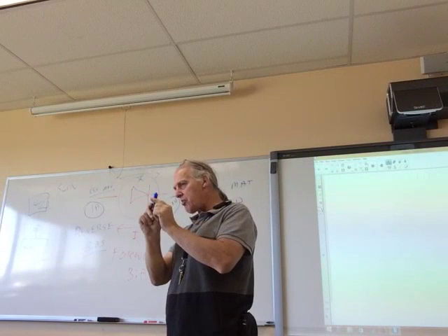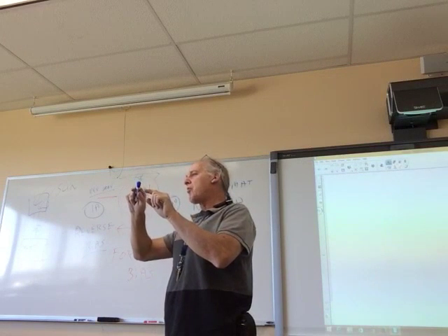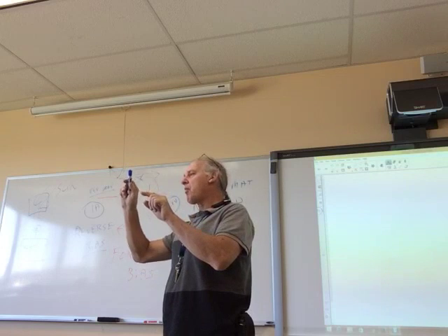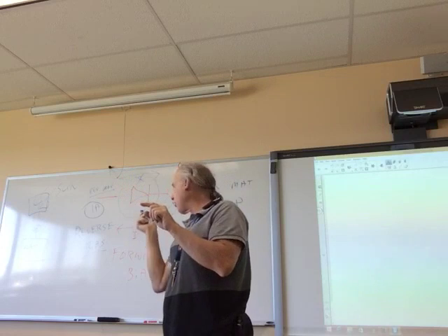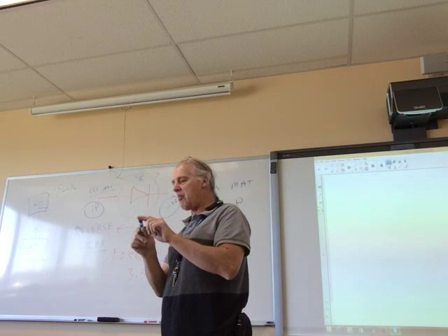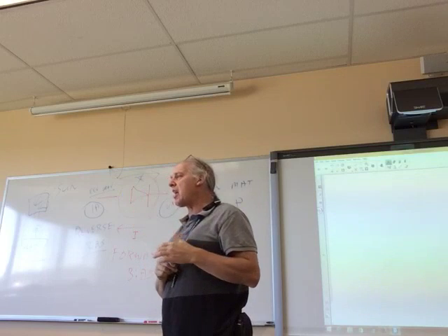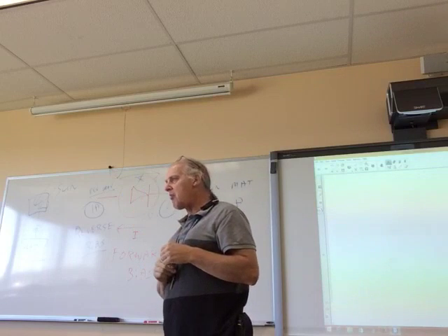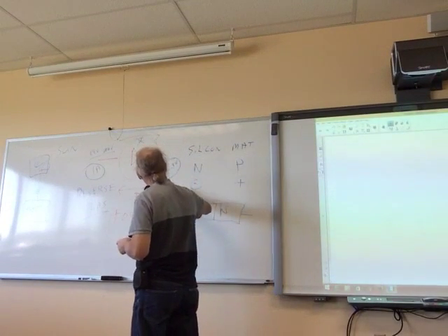At 0.7 volts, then you'll see the diode start to flow current. And it will flow current up to 12 volts or whatever voltage you stop at, as long as it's less than what destroys the diode, okay? So the current will start to flow. So you always have to take into account that 0.7 volts. It's called the forward bias voltage, okay?